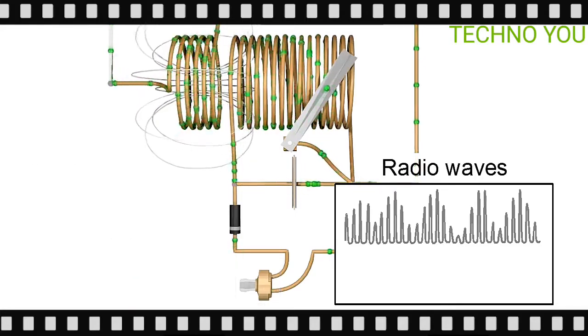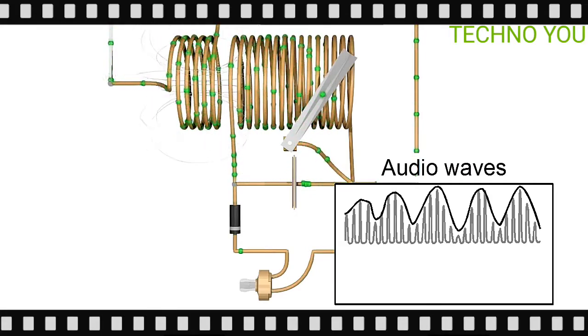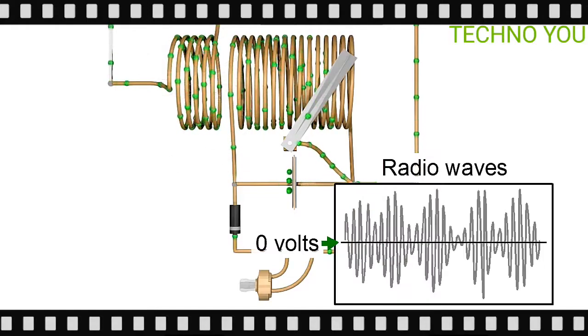So the crystal is reacting not to this higher frequency radio wave, but to this lower frequency audio wave that's sort of built up by all the higher frequency radio waves. Another way of looking at it is to look at only the waveforms.